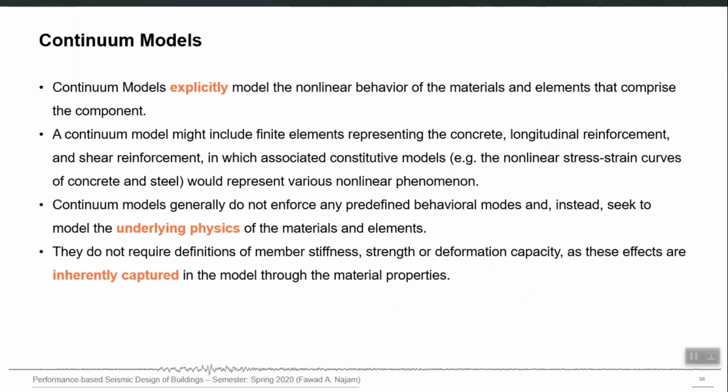So let's have a quick discussion about three of these approaches. Continuum models explicitly model the nonlinear behavior. They try to model the behavior at the most fundamental level, right? They are not trying to lump something and account implicitly something. This is an explicit model. So whatever is the real geometry of that element, you will model with very small elements, and each element will be given a realistic material behavior. So whatever is the material disintegration, cracking, yielding, it is expected to capture that behavior because it is composed of all those small elements.